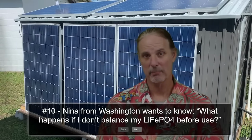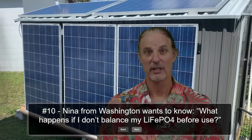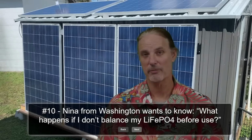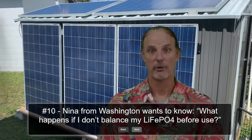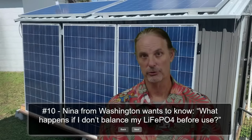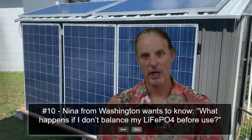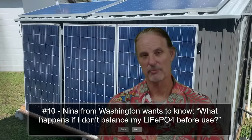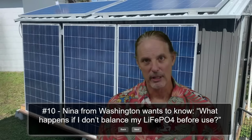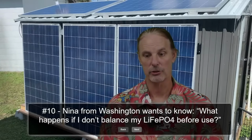If you're adding them to another bank, I'll warn you again, you do need to make sure that the batteries are within a certain variance of the batteries you're connecting them to, so that you don't have a large amount of power transferring from your existing bank to the new battery, or vice versa. That could cause you some serious problems. And make sure, of course, you have proper fusing, and double check your specs from the manufacturer to make sure you're not breaking any of their input and output rules, as far as how much amperage it can take, how much it can charge, and how much it can discharge.